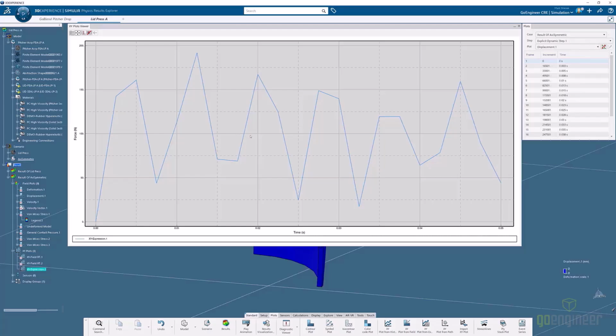And that's probably because of that lower gasket lip being too long and the pitcher kind of angling down. So we need to do a little work on this model to really get that lid straightened out. So we have to revisit the seal design, but we're able to see that up front before we go to prototype this. So this is invaluable information to save us money on cutting that mold. We are able to see that virtually.